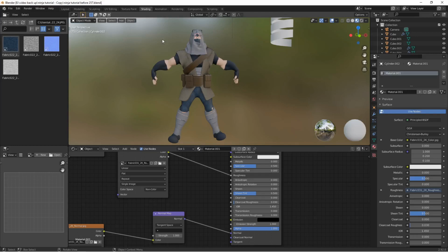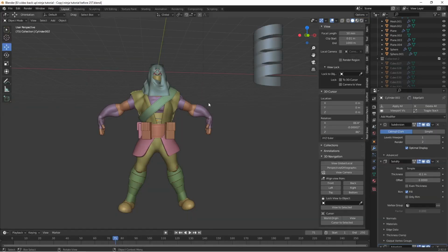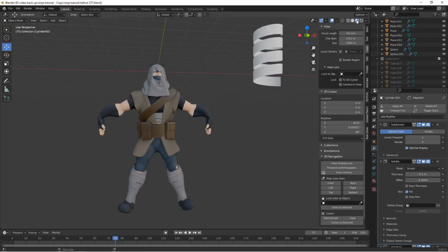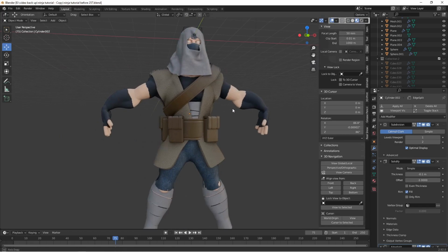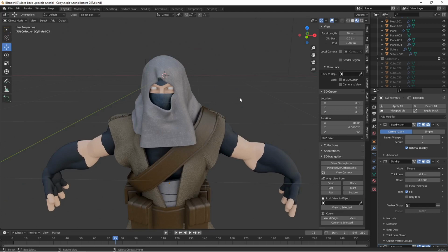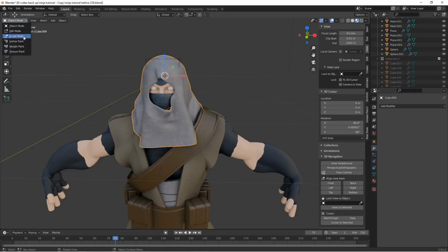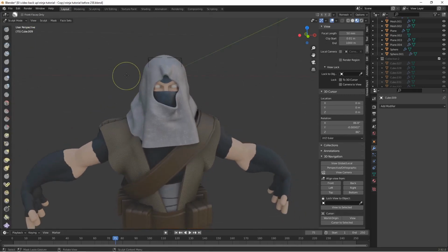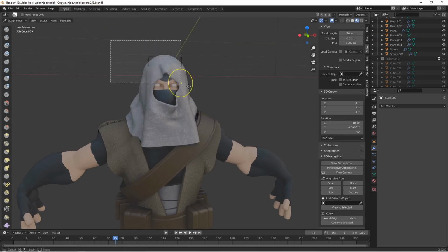Okay, what we're going to do now is go to the upper left to layout. We're going to make some adjustments to our mesh. Okay, we're going to select here, go to the upper left, go to sculpt mode. Here in sculpt mode, where we want protected, which is this top part, we'll press B and then box select this here. So now we won't be able to move that geometry.